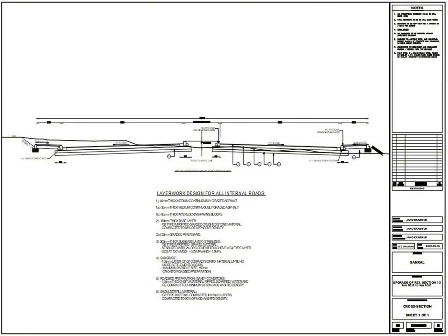For proper stormwater drainage, the road surface will be sloped with a 2% fall to the left with a gutter and curb installed on the edge. Right behind the curb there will be a 1.5 meter wide raised walkway sloped with 2% towards the road. Curb inlets will be installed in strategic places and also at a maximum of 200 meters from each other on both sides of the road.